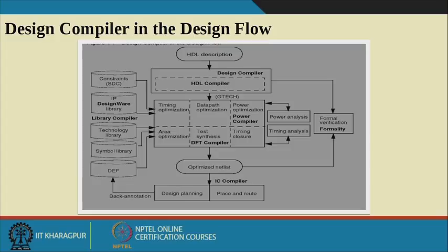In Design Vision, whatever you do in the graphical mode, the corresponding command runs in the background. Actually we are running in command mode, but we have not typed the command at the command prompt. Whatever we do in the graphical mode, that command will automatically appear in the command prompt. So this is the design flow of Design Compiler.